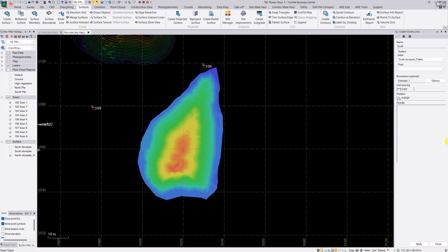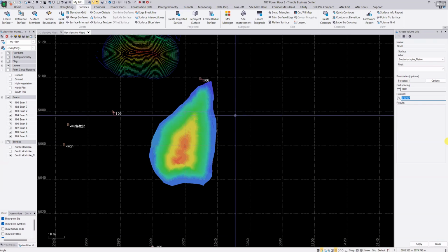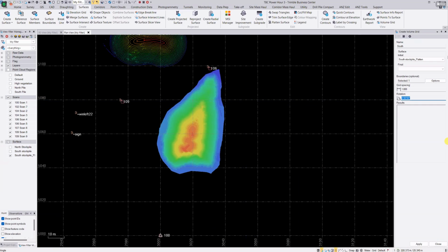So over here, you can see that's a small area, 1 meter grid. That will give you a calculation. It will give you a result, and you can compare it and see when you start tapering off in your results, and test it that way if you want to see how accurate the volume calculation is that you get by changing the grid size. Some guys like to have a smaller grid, get more accurate. Again, timing for the calculation will take longer the smaller your grid is.